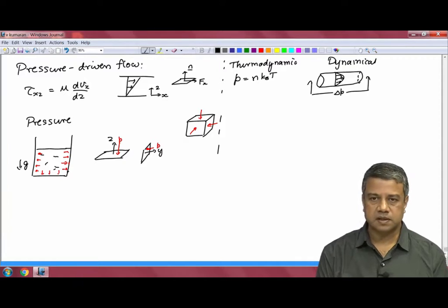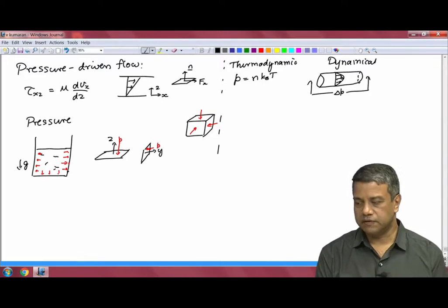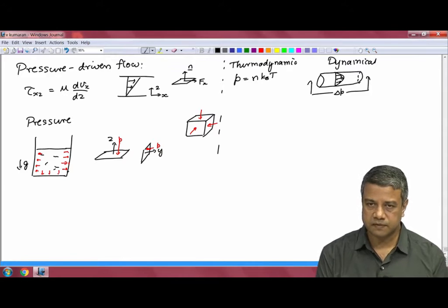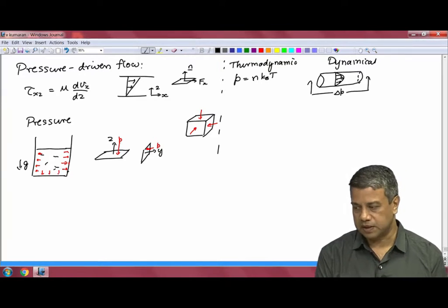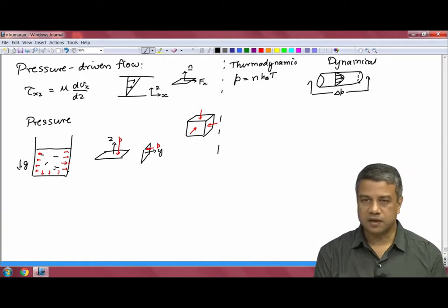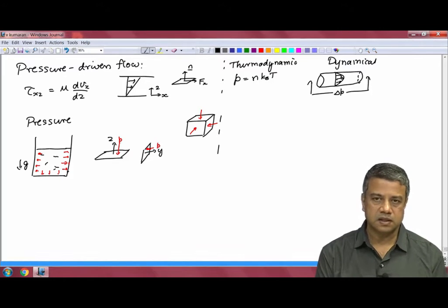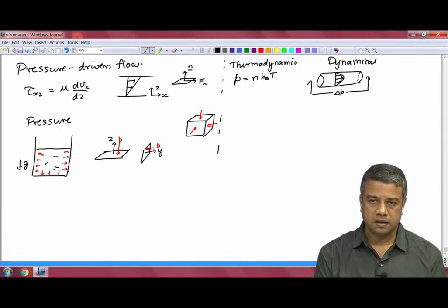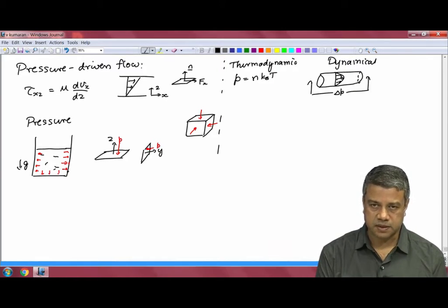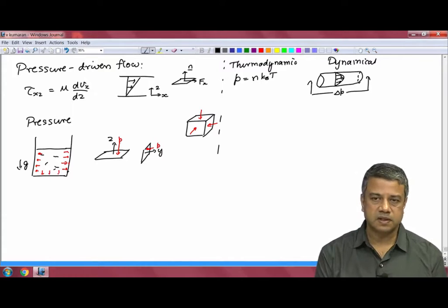For the dynamical pressure, in order to compute the fluid velocity, if I add a constant pressure everywhere in the field, the velocity will not change, because the difference in pressure between 2 points has not changed when I have added a constant pressure everywhere. So, therefore, for incompressible flows where the density is a constant, the velocity is driven only by differences in pressure or gradients in pressure. The absolute value of the pressure does not matter.